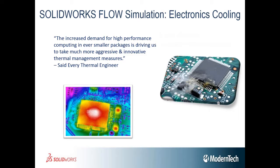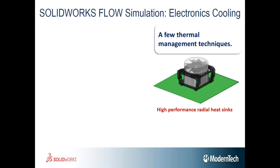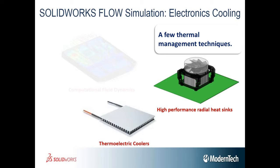So let's look at a few thermal management techniques. We have the classic heat sinks. In this case, actually, one thing we're going to look at today is a radial heat sink, and this is a high-performance heat sink here. We have thermoelectric coolers, and thermoelectric coolers have been around for a while, and they're really great at achieving really low temperatures. However, they cost a lot, and when I say they cost a lot, I mean in energy.